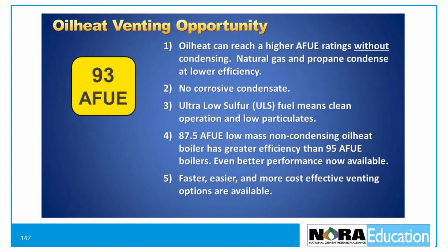Oilheat has a unique venting and efficiency advantage as it can reach up to 93 AFUE without condensing. This is good news because high efficiency can be achieved without corrosive condensate. Ultra-low sulfur fuel is now standard, delivering extremely clean operation with virtually no particulate emissions.